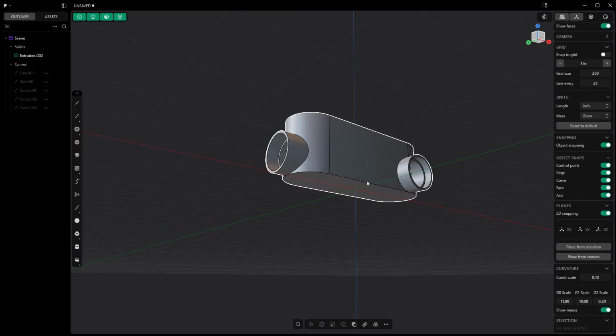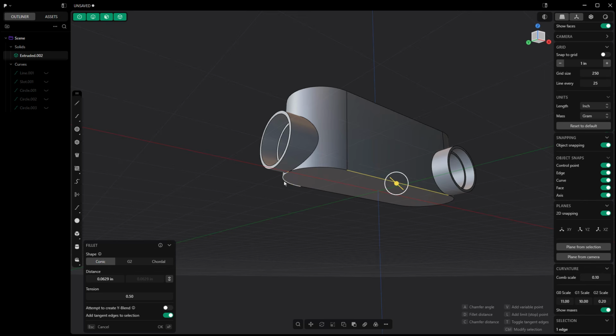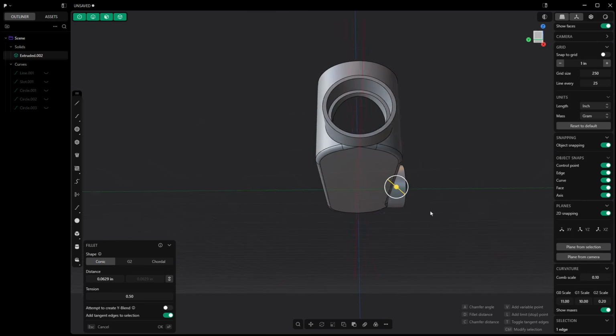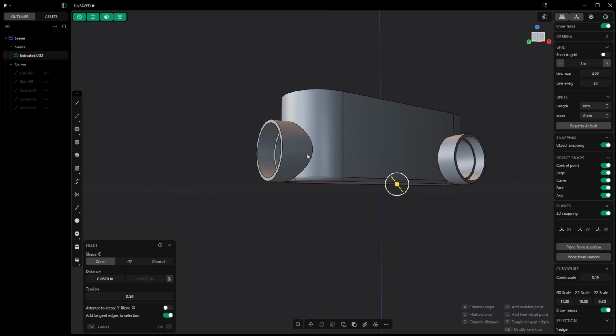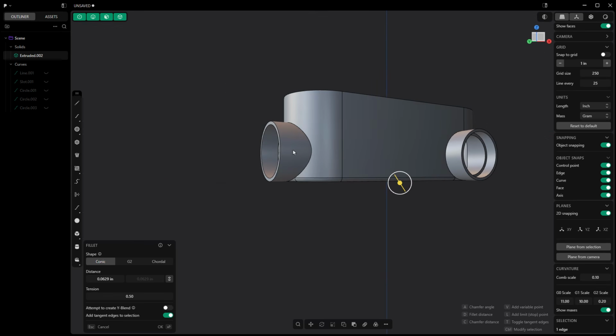The last thing that we need is just kind of a rounded edge on the bottom. So we're going to pull a fillet out, hold down Control to select the other side. And these typically don't have a fillet around the inlets that go into the conduit body because there is a parting line here. That would make manufacturing a little bit tricky. But again, for our purposes in Plasticity, you could very easily add those if you wanted to.